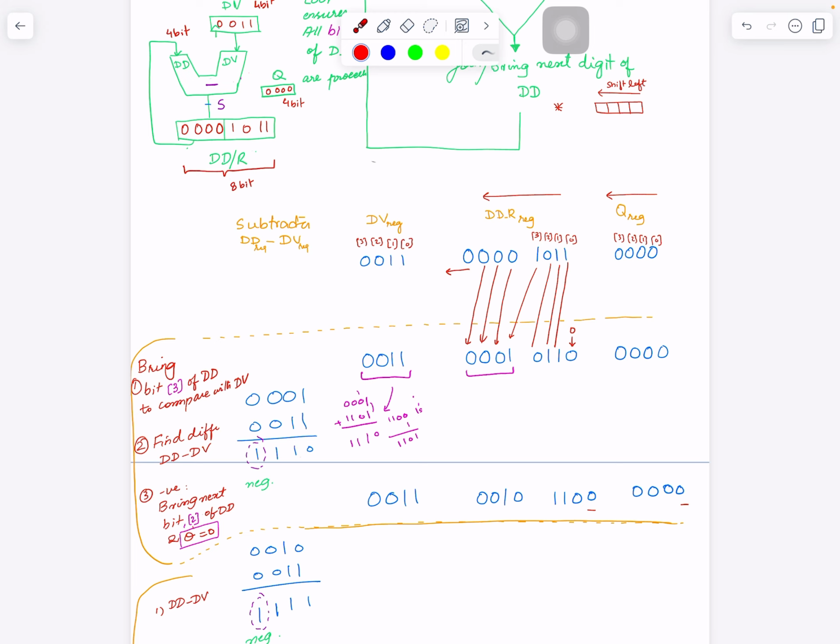There's another way you can do quick subtraction. So you say 1 minus 1 is 0. 0 minus 1, you cannot do that. So you bring a 1 here, which becomes 1, 0. Okay, 1, 0 is 2. So we bring from here, it makes 1, 0. You have 1 left. From here, you need to bring 1 here, it becomes 1, 0, but you have 1 left. So from 1, 0, which is actually 2, 2 minus 1 is 1. There's 1 left, 1. There's 1 left, 1. So either you do the typical method, or you do a kind of mental subtraction. So you can do it quickly, instead of taking the 1's complement and adding 1, you can do this.